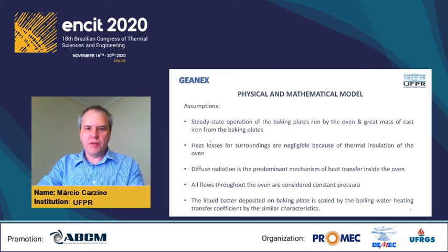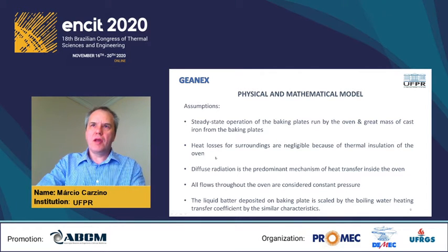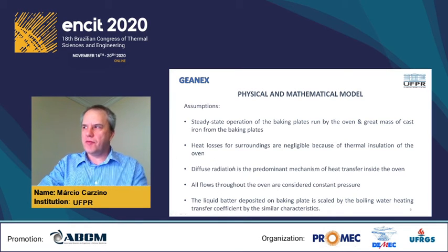The assumptions for the development of the physical and mathematical model are a stationary state, and diffuse radiation is the predominant mechanism of heat transfer. We don't lose heating to the surroundings. The flows and the pressure are constant, and the liquid batter deposited on the baking plate is modeled by scaling a boiling water heat transfer coefficient by similar characteristics.